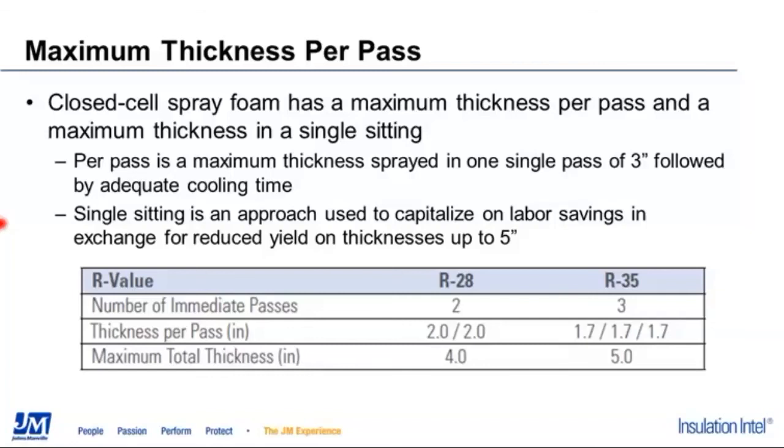Well, there comes a point where you're not left with enough plastic anymore to actually sustain the normal cyclic nature of daytime, nighttime. So every single day, all of these millions of little cells are expanding as they heat up, and then overnight they're contracting. And I want you guys just to take a moment and think about, when you get ready to throw away a credit card, you bend it in half, you bend it back out straight, it's still plastic, it's still intact, you bend it in half again, you fold it back out straight. You do this enough times, and eventually that credit card breaks in half.